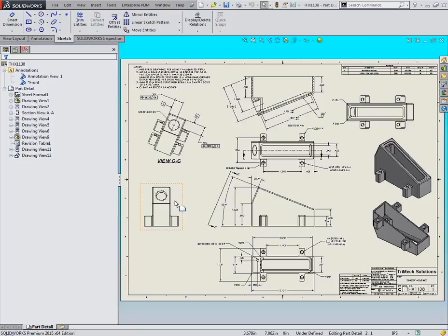Sometimes we have to inspect to that PDF file that our customer or our vendor has sent us. And the standalone SOLIDWORKS Inspection tool will also allow you to automate and streamline the process of ballooning and generating inspection reports synchronized with those characteristic numbers on the balloons. Finally, the standalone version of SOLIDWORKS Inspection also has a bundle level called Inspection Professional that allows you to import your measured inspection data and even pull in some CMM reports. We'll talk about that at the end.